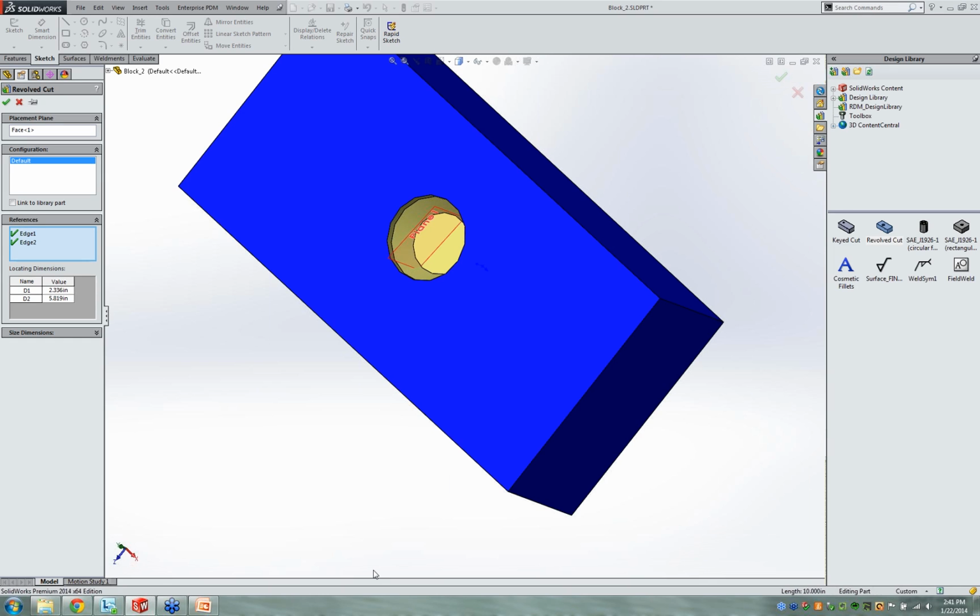Again, the important part is being very careful with your references there. What we're creating and understanding why a reference is getting created. Kind of the way to troubleshoot that would be to backtrack through and see which features are creating what references. You know, if we delete this dimension, does our reference go away? And some of these you'll have to work backwards on. But this is a process that can be followed for any kind of complex library feature.